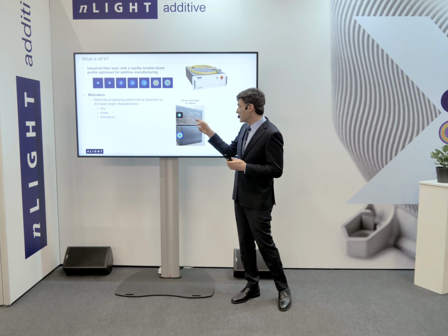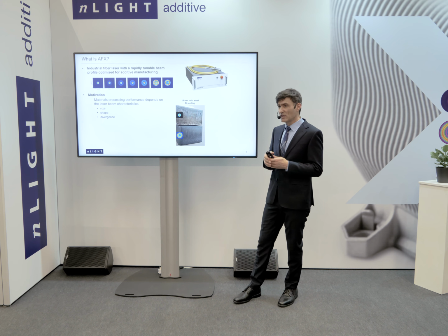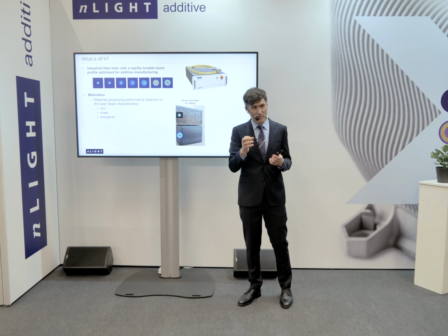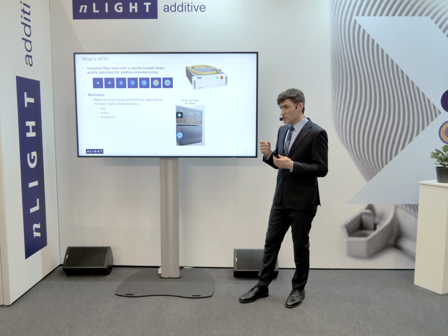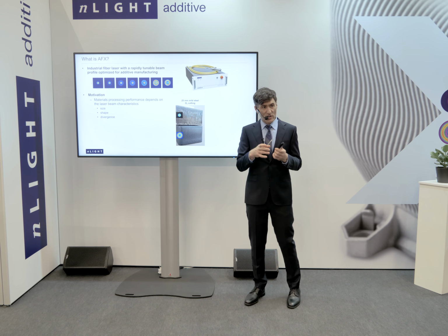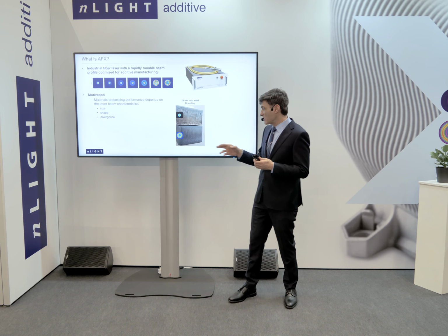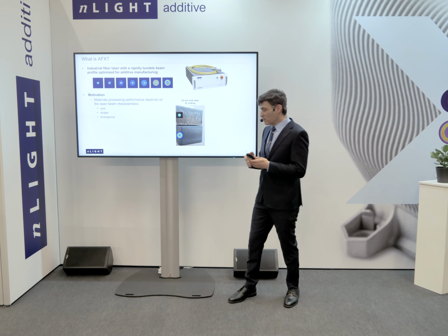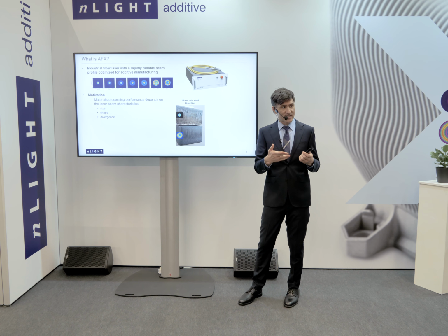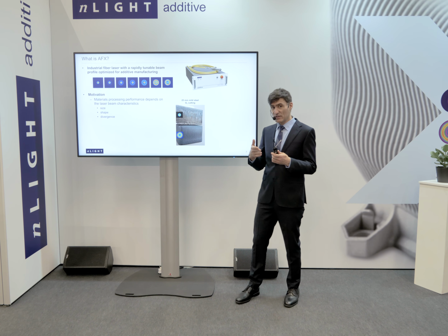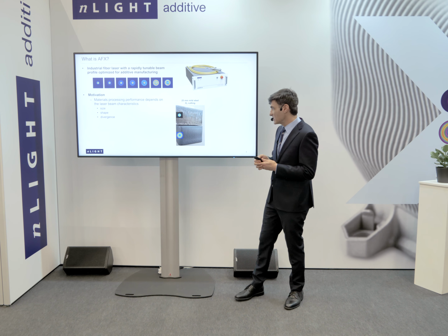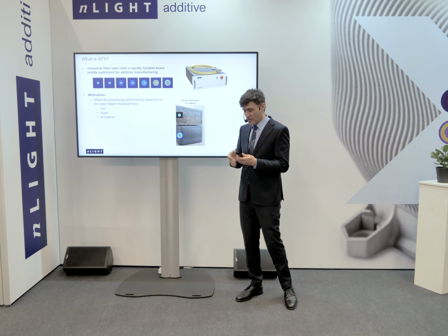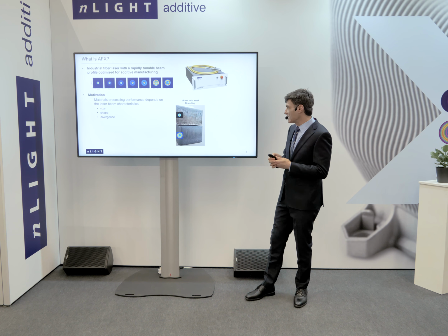Here's a 25 millimeter mild steel sample cut with a standard fiber laser from 100 micron fiber, and you can see the poor edge quality. It's been shown that by going to a larger 300 micron ring-shaped beam, one can get much better edge quality, in fact rivaling a CO2 laser, which has allowed fiber lasers to then displace CO2 lasers in this last important application, but they couldn't do so before they had this beam shaping capability.